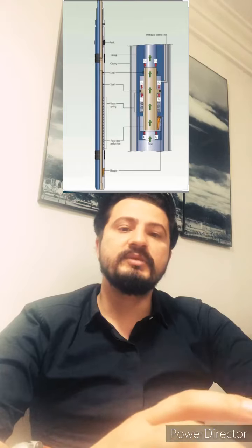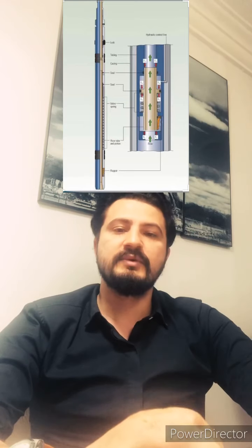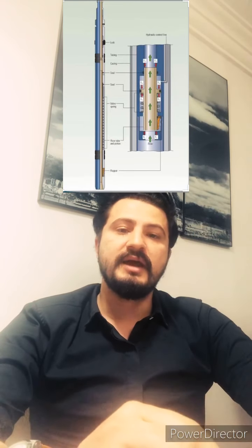Each type has a separate tool to do the lock out or lock open for the flapper. Once locked open, a separate communication can be used to establish hydraulic communication with the control line, to facilitate the insertion of a wireline retrievable safety valve deployed hydraulically.